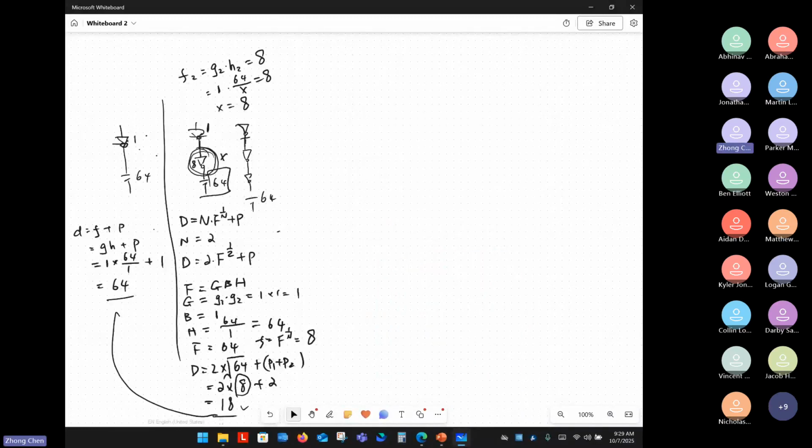Okay, so we have 8 as the input capacitance. So P is equal to 8 times 3 over 2, and N is equal to 8 times 3 over 1. So that is the P and N size for the inverter. Okay, so we can calculate the two stage, which is actually much better than the single stage.